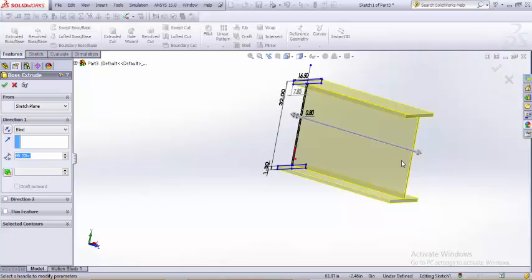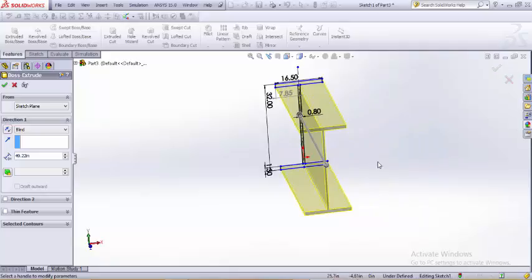If you use any kind of loads on this axis, it would tend to bend because this has the least radius of gyration, and the bending would be on these 2 sides, on the opposite sides like this, because these would turn into something slender, and for long beams, the critical slenderness ratio would be exceeded.